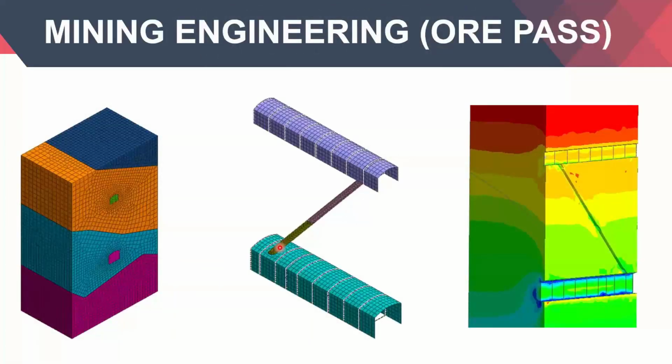Now coming to underground mining. One of the examples is ore passes. This is an ore pass for an underground metal mine, created in very good rock, almost intact gabbro. You can see the rock was so competent that even the main haulage ways only needed some steel arches and a very thin layer of shotcrete. There's no rock bolt needed in here.